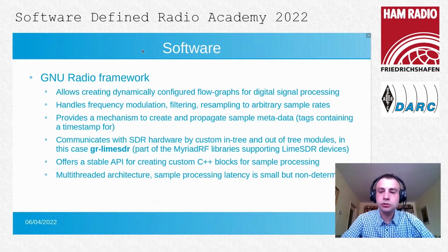This framework provides a mechanism to also create and propagate sample metadata, which are tags associated to samples containing a timestamp, which in our case will prove crucial in order to do the time synchronization required by DMR. GNU Radio communicates with SDR hardware using custom in-tree and out-of-tree modules. In our case, I have used GNU Radio LimeSDR, which is part of the myriad RF libraries supporting LimeSDR devices.